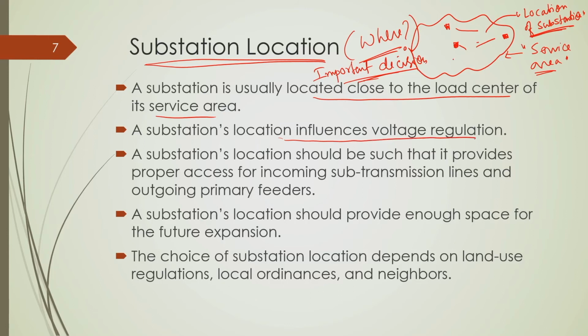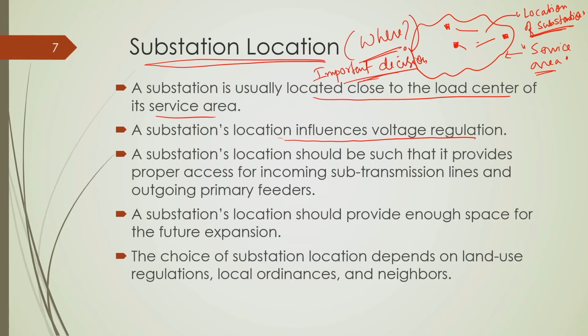If you have a substation located far away from a particular load or customers, then these customers will definitely experience some voltage problem, particularly during peak load conditions. Also, the substation location should be such that it provides proper access to the incoming sub transmission line and outgoing primary feeders, because as you know, a substation basically connects the incoming sub transmission line to the primary feeder.